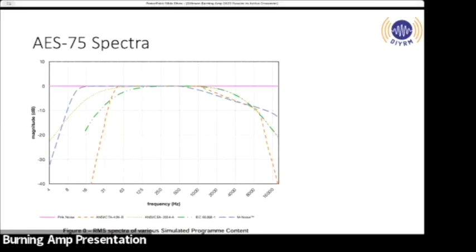In music, this is AES75, otherwise known as M noise. It's this dashed curve. Your power density starts dropping. This is a phenomenal test signal for those that haven't used it before. Your power density starts dropping, and you just don't have that much power dissipation in the tweeter anyway. That's why that tweeter that is permanently damaged at 5 watts can be used in a system rated for 100, 150, 200 watts. All right.